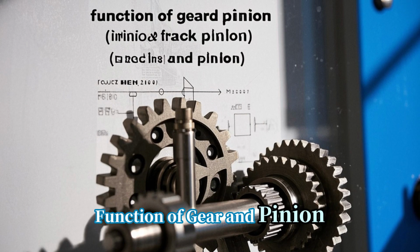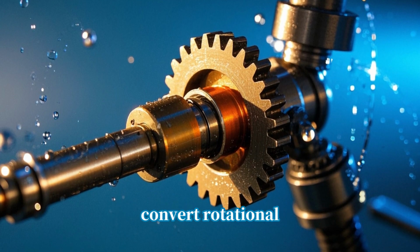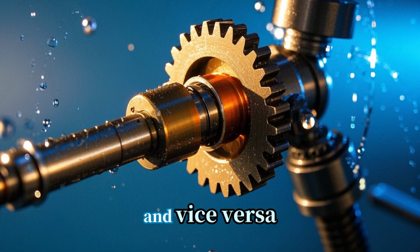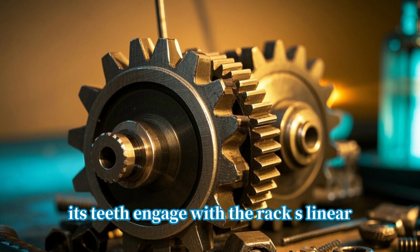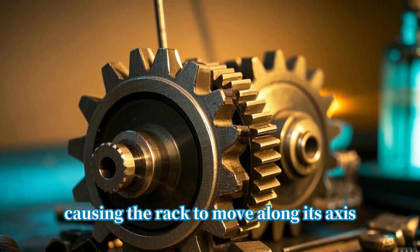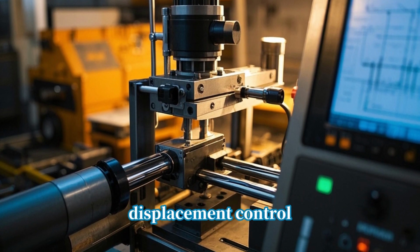Function of gear and pinion rack and pinion. The primary function is to convert rotational motion into linear motion and vice versa. When the pinion rotates, its teeth engage with the rack's linear teeth, causing the rack to move along its axis. This enables precise linear displacement control.